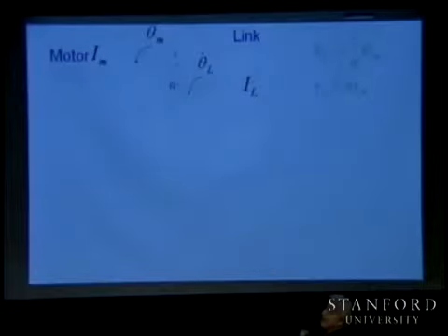And this something is... Twice the inertia of the motor. So you mean in general this is n times the inertia of the motor? That's what you mean? Yeah, so it is n times the inertia of the motor, which is similar to the torque increase. The torque at the link is n times the torque at the motor.